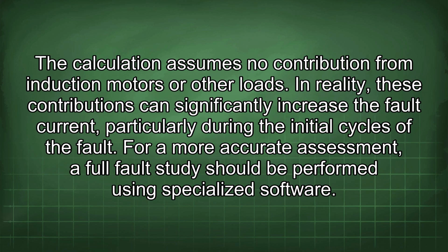The calculation assumes no contribution from induction motors or other loads. In reality, these contributions can significantly increase the fault current, particularly during the initial cycles of the fault. For a more accurate assessment, a full fault study should be performed using specialized software.